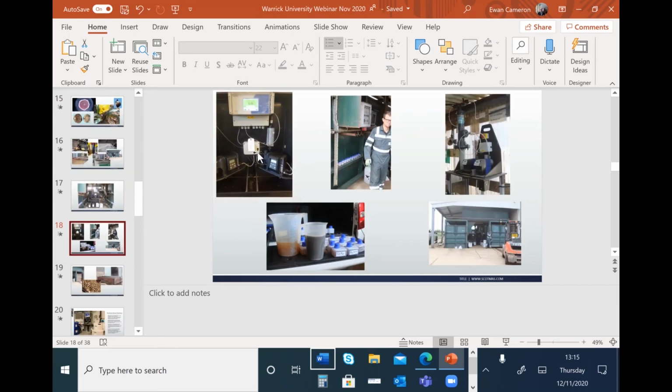Again, this is just a close-up now of the system here, where we've got two digital dosing pumps, because obviously we're setting it down into parts per million, which means we're using mils of chemical per ton of water. So they need to be digitally controlled. And we have an analyzer here, which gives us a visual detail on what exactly the part per million concentration is in the tank.